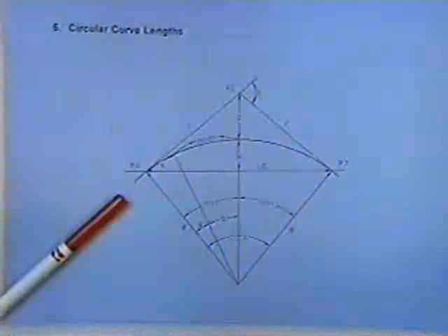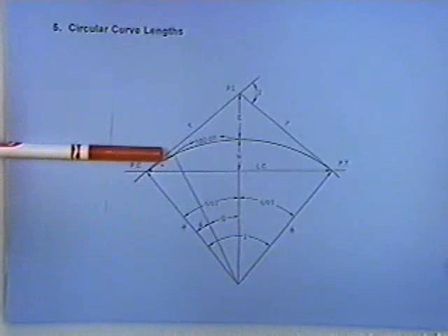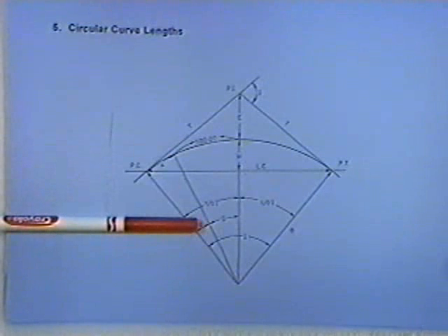You'll also see it referred to as delta in some surveying textbooks. More commonly, though, I think you'll see it referred to as I. Now, in highway design, there's a couple of different ways to do it. Most of your textbooks will use something that's called a chord definition. And you'll note in this drawing there is a 100-foot, I should say arc, I said chord, it's a 100-foot arc that's drawn out there, and that's really a distance of 100 feet along the arc of that particular horizontal curve. And down towards the bottom of the drawing you'll notice something called D, which we refer to as the degree of curvature.